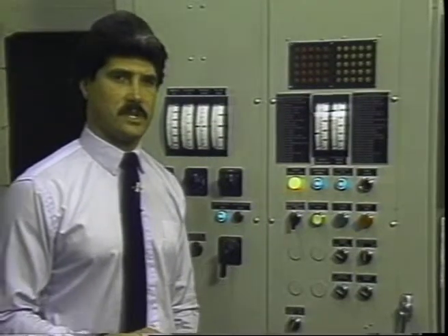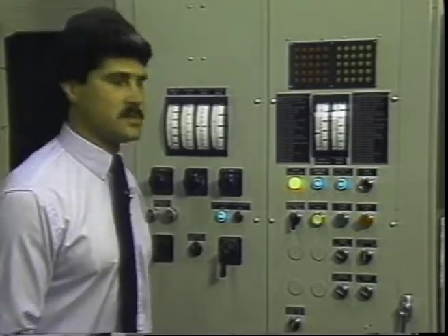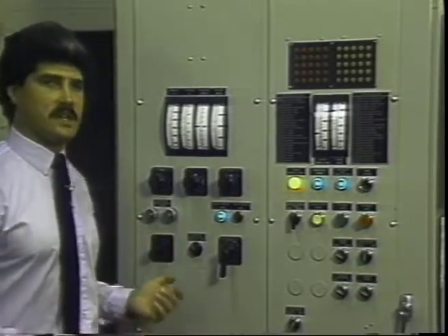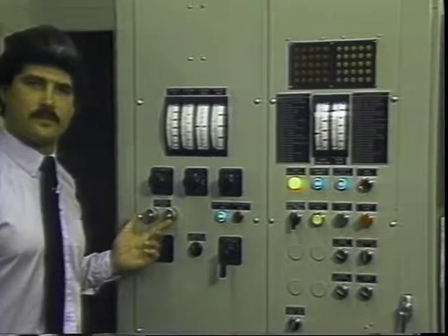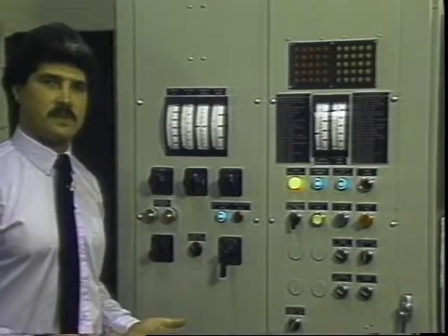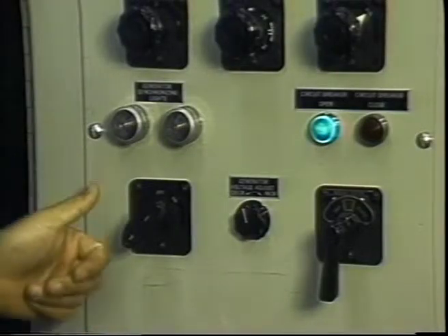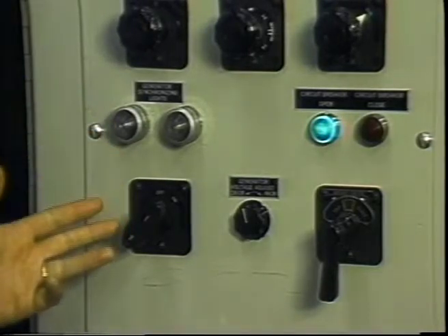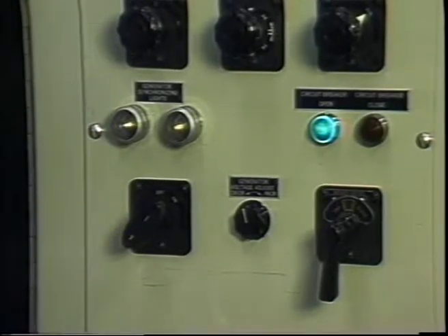With voltage and frequency properly set for no-load conditions, move the synchronizing switch to the on position. This causes these synchronizing lights to cycle on and off together. Adjust the generator speed until the lights cycle dark for about 4 seconds. This 4-second dark period indicates that the generators are operating very close to the same speed.